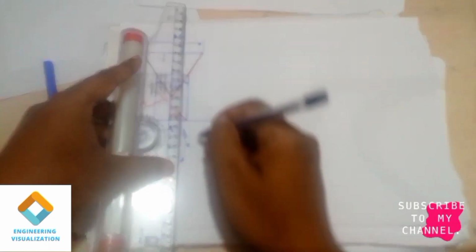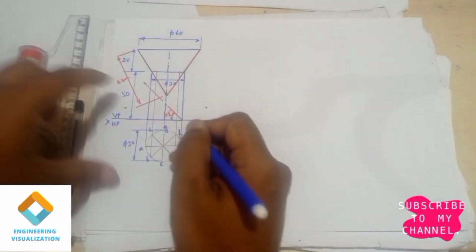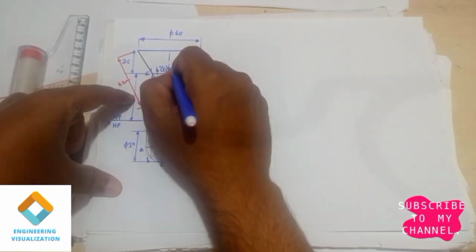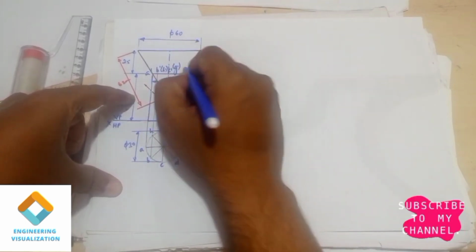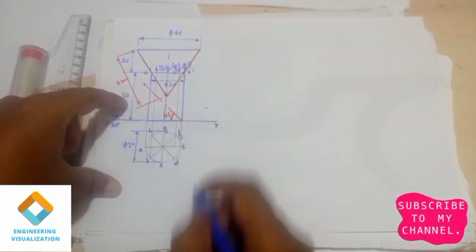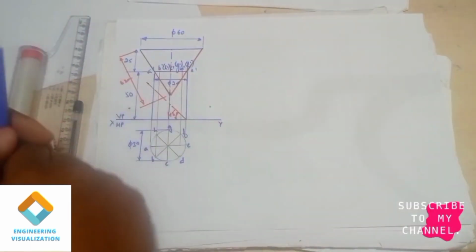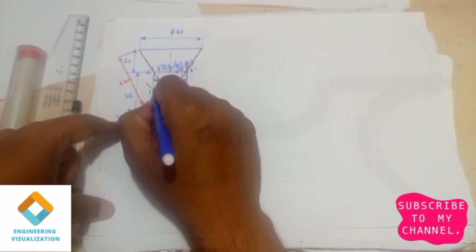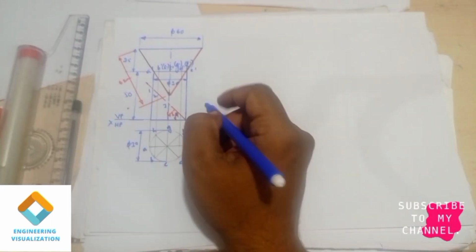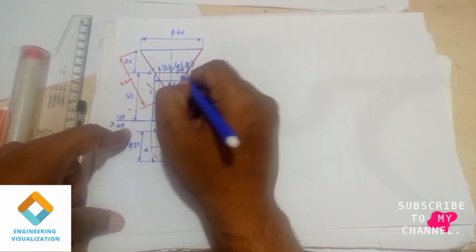So draw the projection lines. Now write the namings. Here A dash, B dash, C dash, D dash and E dash are visible. H dash, G dash and F dash are not visible. Those are written within brackets. Now we need to write the cut points. Here the cutting is exactly at lines 1, 2, 3, 4. You can see wherever the section plane is cutting. So we are writing again here 6, this is 7 and this is 8.